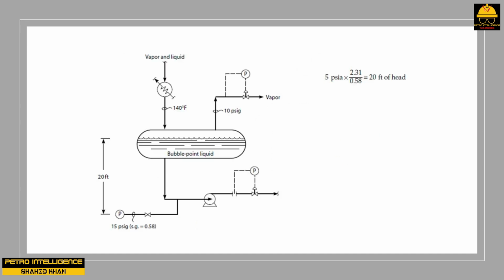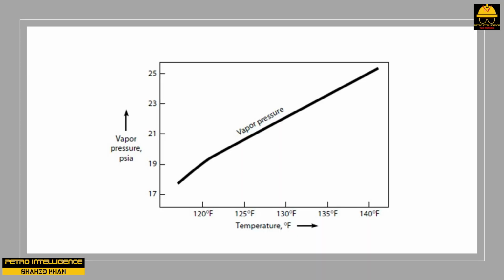Let's now assume that we wish to pump 300 GPM, not 250 GPM. If we open the flow control valve shown in picture, the flow will momentarily increase. But within a few seconds, the flow will become erratically low as the pump begins to cavitate. The problem is that, according to picture, we require an additional 6 feet of NPSH to increase the flow from